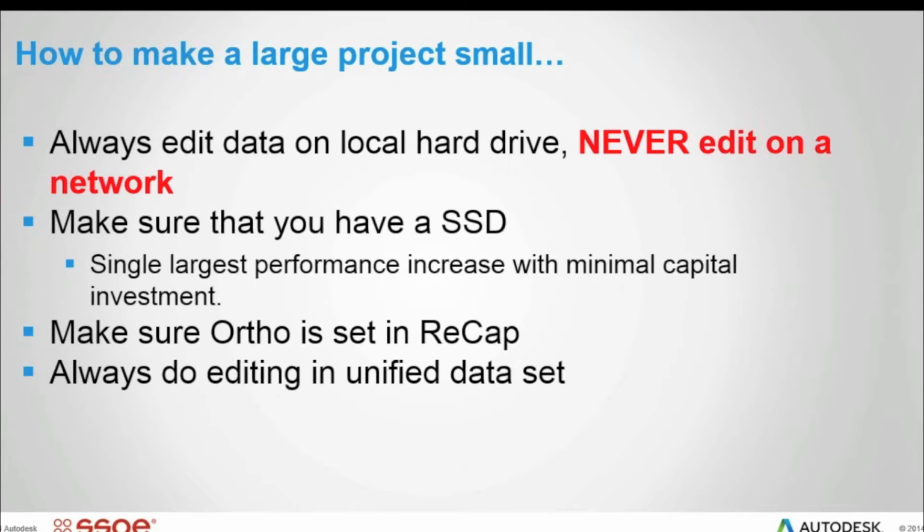And the last point on this particular slide, make sure your data is unified. And what I mean by that is when you have your scanner and you take 60 shots in a project, each shot creates its own RCS file when it's converted into Autodesk ReCap. If you start chunking up or splitting data into sections without unifying all of those RCSs into a single one, it's going to take that process of exporting and it's going to multiply it. I don't know what the multiplier is. It's not necessarily exponential, but it certainly is a lot longer.